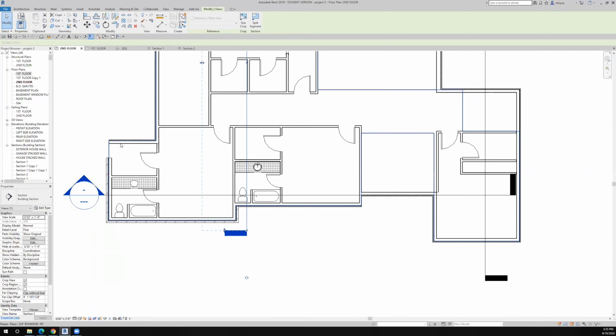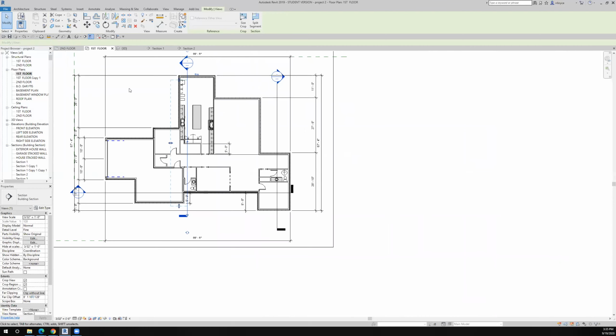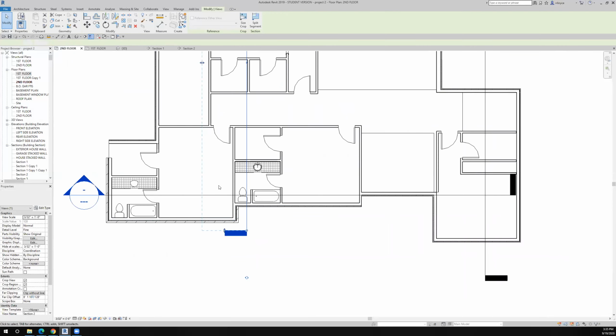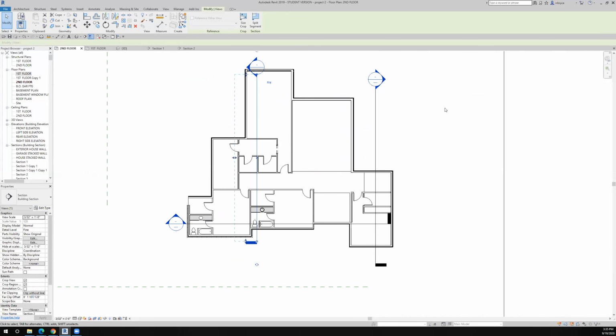And I also see that I have an issue here. So I know I have an issue here that I have to deal with. And this, I think, is a stacked wall. Yeah, so I can't continue it any farther back here, because if I look at the first floor, that stacked wall stops right here. If I drilled that stacked wall back this way, then it would put, on the first floor, it would put something here. So I need to put a second floor wall there. But right now we're working on bathrooms. So there's our second bathroom, and that was really easy to put in. And so you're using the copy command and duplicating the things that you have.